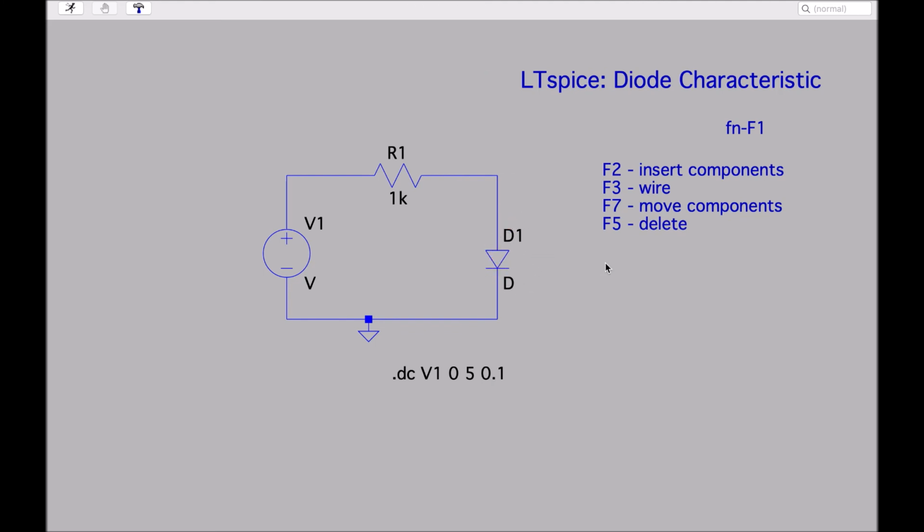And so how do we alter our graph so that we're just plotting what's called the VI characteristic for the diode only? Well, the answer is to do with those nodes that we mentioned before. We want to measure this voltage here across the diode relative to ground. And so the node that I'm interested in is this one here. And it happens to be V(N002). It says at the top of the screen there.